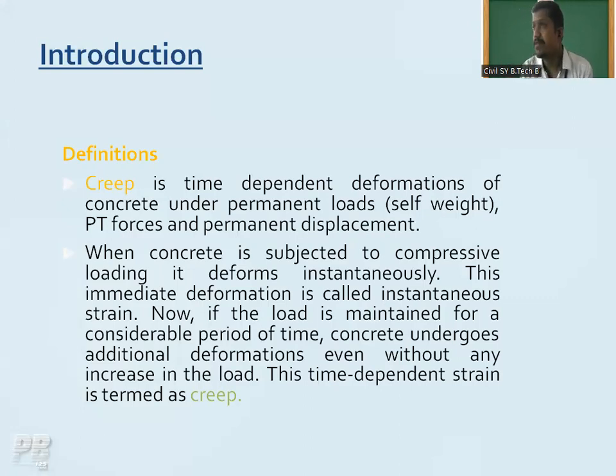And always remember, creep is a time dependent deformation. It is time dependent because, as I told you, with respect to the age, the creep is going to happen in your concrete body. So for how much time, sir, is this creep going to last? It may happen that for a concrete structure, the creep may last up to 100 years also.